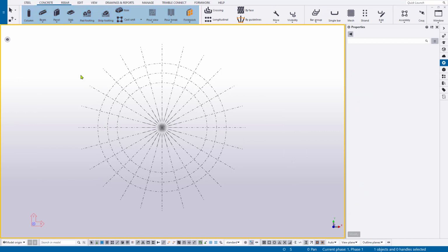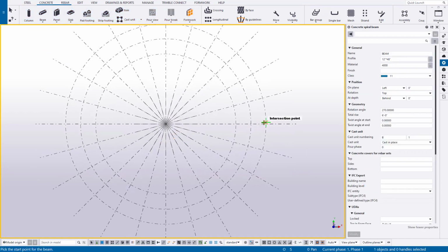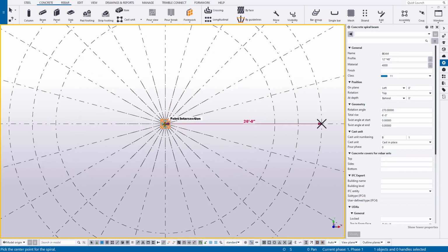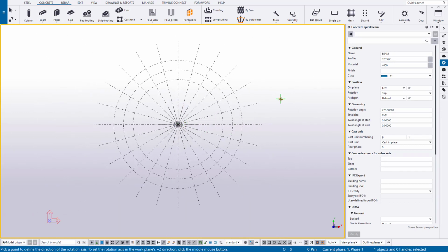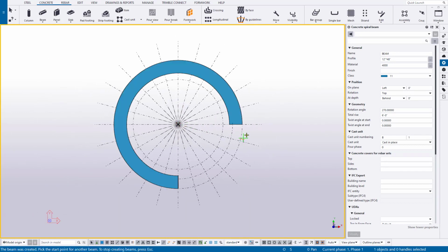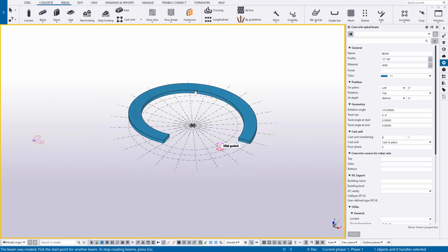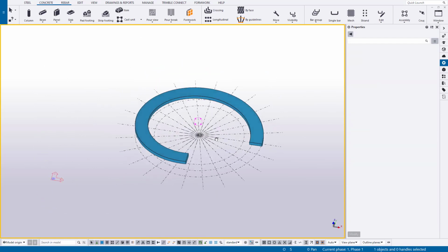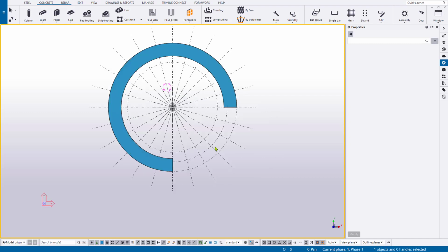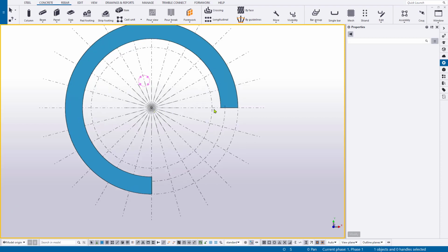Now, back to what we were saying: concrete ribbon, beam dropdown, spiral beam, start from the outside extents, then click the middle mouse wheel. That's going to go ahead and place the ramp for me. Whenever I'm modeling anything that is cylindrical or round, I like to use these azimuths, and I also model on the cardinal degree, so either 0, 90, 180, or 270.